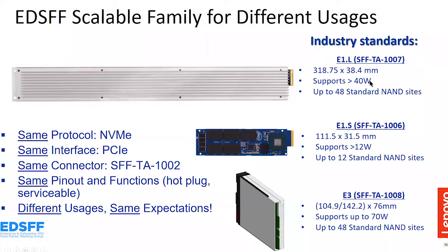And so we have that connector that I was showing you, and then there are also 3 other types that are actually form factors for the SSDs. We have the E1.L, the E1.S, and the E3. So basically, as you were seeing, Samsung had NF1, which is another thing that's not in this group, but Intel had a ruler drive, which is the long one, and that's reflected very similarly in the E1.L after we negotiated all these different form factors and the connector and everything that's in these.